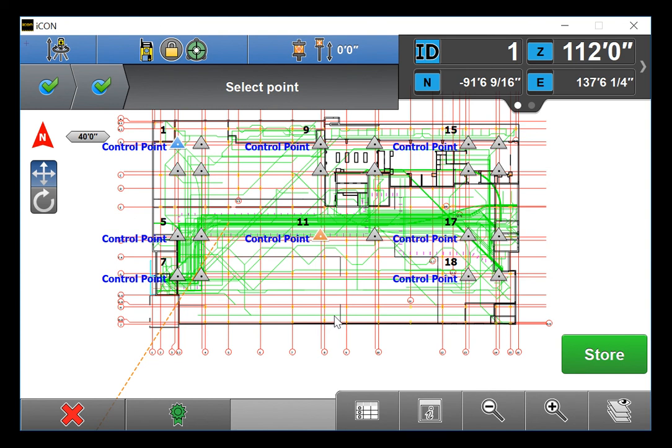You can also use the checks program, which will be covered in a future video, to extract the dimension from control lines to hard objects such as walls or columns, and then use your tape measure to check those dimensions and see if they're lining up. If you find control lines laid out incorrectly, kindly let the concrete layout team know what you found and show them the dimensions you checked to the columns and walls. Then use a different target for your setup.